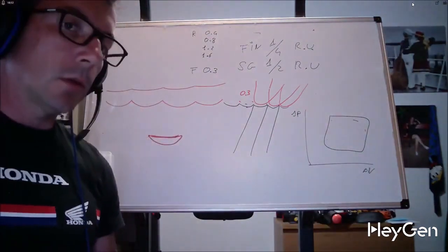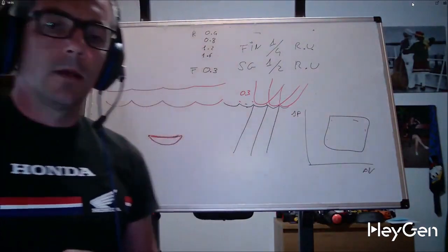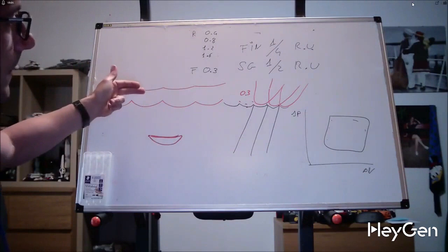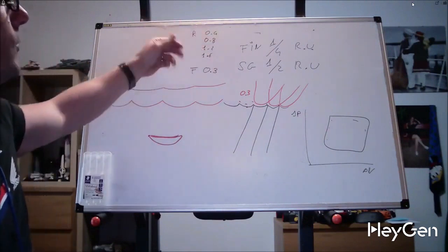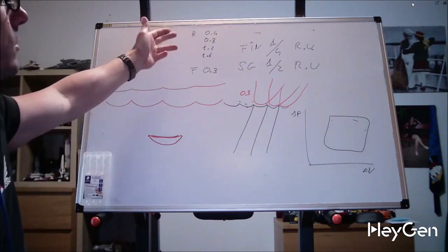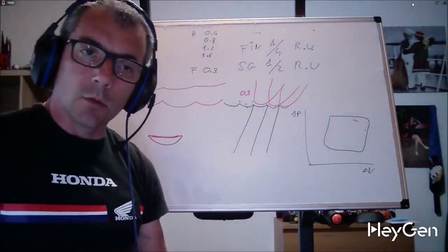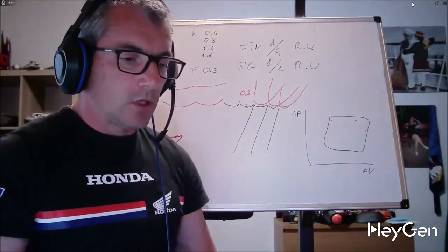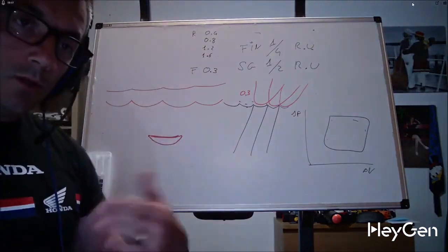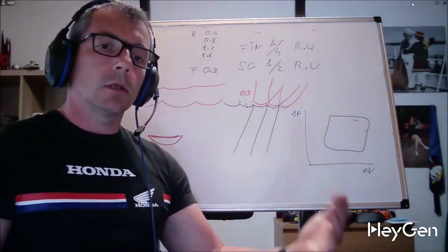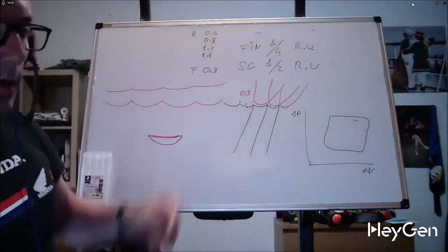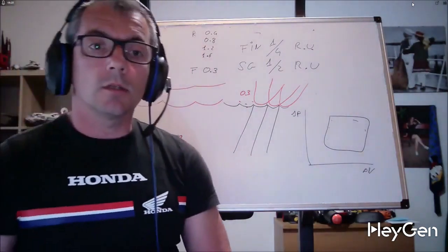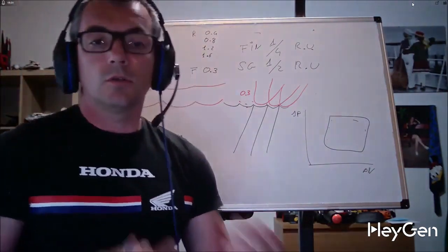So, if I want to do a finishing with a radius of 0.8, I will set the feed to 0.2 for finishing. Okay, let's start like this. Then I go to a technical office, have the roughness measured, check the drawing, and see if I'm within the limits. Additionally, I will conduct a study on the drift of tool life. That is, a tool with a radius of 0.8 after making 100 pieces will no longer have a radius of 0.8, but a radius of 0.9. This does not mean that the roughness will improve because it will wear out.